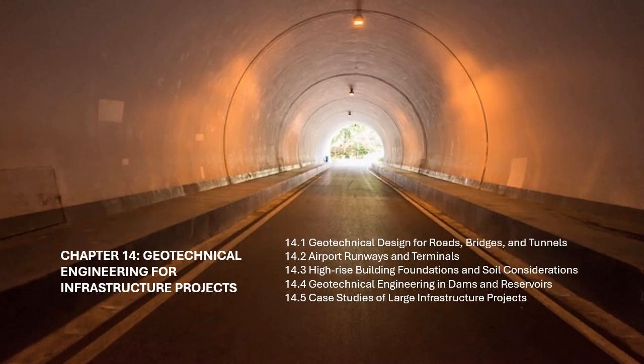Engineering solutions. The project utilized shield tunneling machines (STM) to excavate through the soft marine soils, minimizing ground disturbance and controlling groundwater inflow. Geotechnical engineers also employed deep soil mixing techniques to stabilize the soft clay layers before tunnel construction. A combination of precast concrete tunnel segments was used for efficient construction and safety.